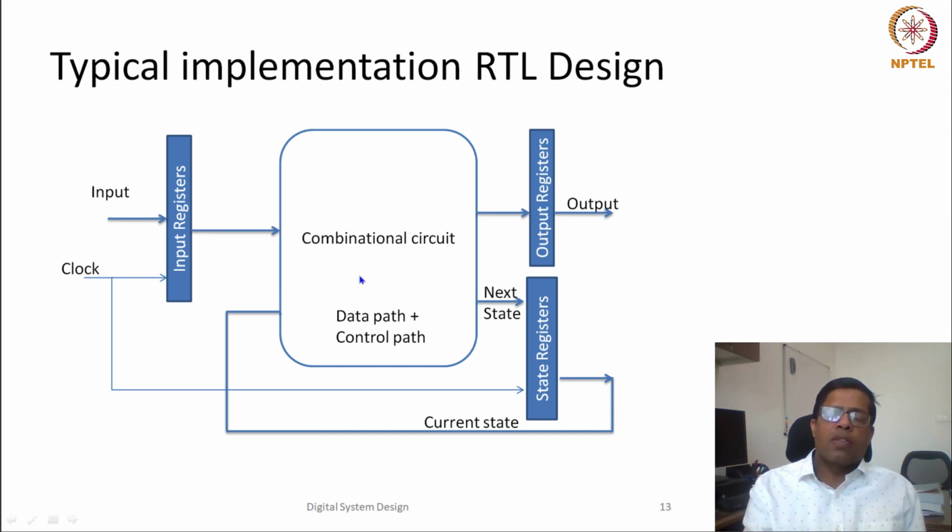So after doing these operations, they are writing to these registers. So wherever these data operations are happening, we call it data path. Wherever this particular data is being triggered, then transferred and copied to other combinational units, and finally getting written to the output register, this overall structure, logic, is called data path.